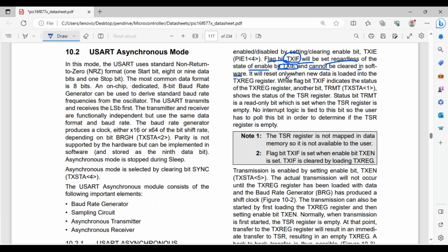So that is the only thing you can do. You don't have to get an interrupt generated when you are transmitting. But if you still want, that is possible. So if you enable the interrupt, once you're done transmitting, you can have TXIF set with 1. So if you want, you can have a message printed and shown that the transmission is done. Clear?